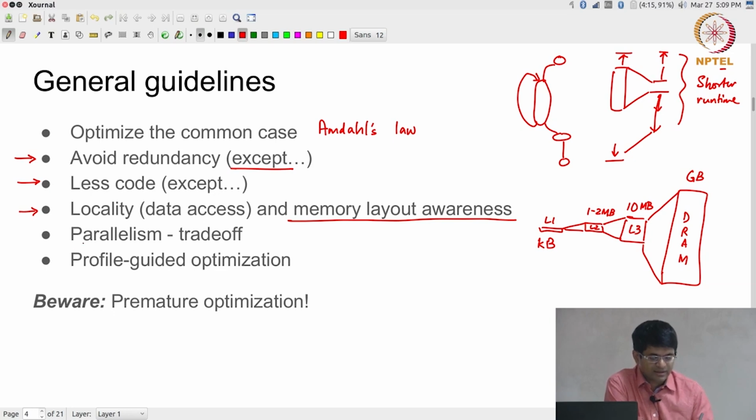There is finally this concept of parallelism, which once again we will need to understand quite well, because in our case parallelism is even more of a concern than for general compilers that target CPUs. In CPUs, at most you have a very limited amount of parallelism because your processing units are quite few, whereas in hardware potentially you can create as much parallelism as you want. How do you make use of that? Of course, it is a trade off, because the more parallelism you have, the more hardware you are using, or more instructions are being used in software at the same time.